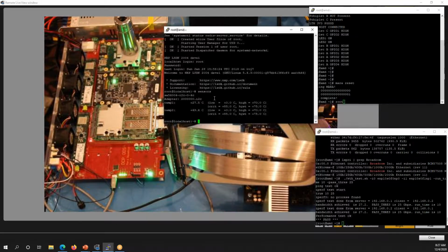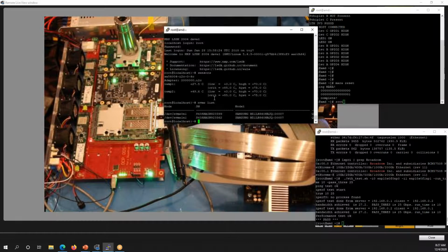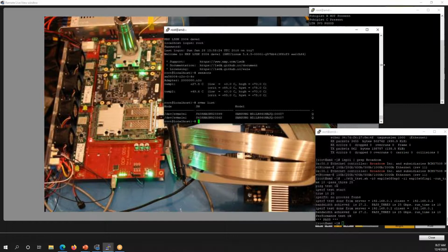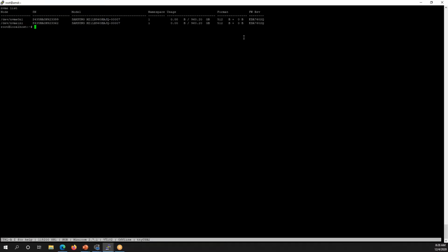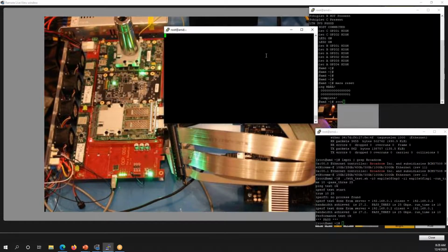And then we also have the NVMe command that you can execute, where you can see the Samsung interface. So you can see that the NXP LX2 is recognizing the two Samsung modules that are there. Each one is a terabit link, and you can see all the information that is there. So that is about the NXP Pitchlet bring-up test that we have done.